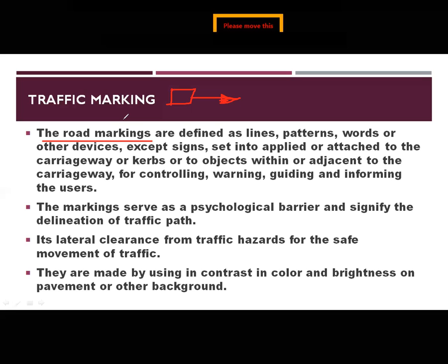Okay, the first one is the traffic sign. A traffic sign is the major part, a symbolic representation of whatever instruction the authorities want to provide to the road user, provided in a simple way. Some traffic signs are regulatory, which is mandatory, some are warning or cautionary, and the third is informatory. These signs must be followed.